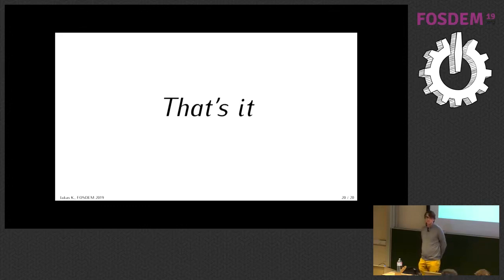I propose one more question and we move on. If I want to use a part which is absolutely nowhere available, what's the workflow to create the footprints and everything? Okay, so the question was what to do with parts that aren't orderable. The pools in Horizon support inheritance. So you can just create your own pool, define your personal stuff in there, and then tell that pool to include the global pool, and then you can just have parts for yourself.